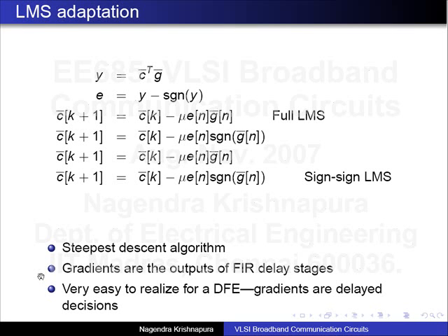So in decision feedback equalization, we are basically taking feedback. Yes, that is true to some extent. In fact, the biggest challenge in decision feedback equalization is to close the loop within one cycle. But because it's digital, it's a little easier than if you make a full IIR filter. And secondly, it offers so many advantages that you just do it.